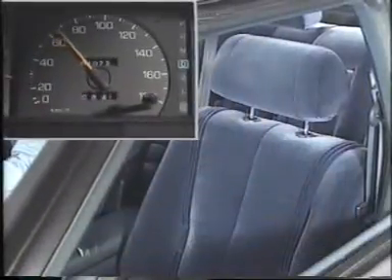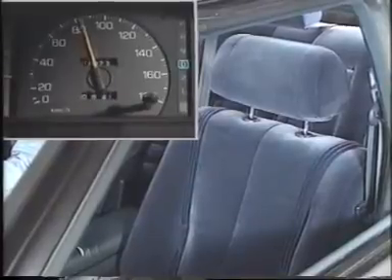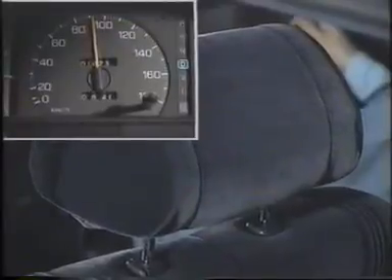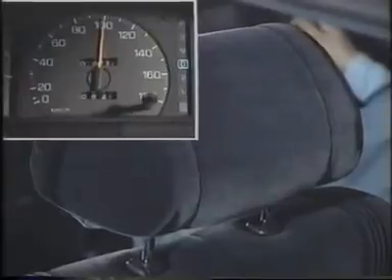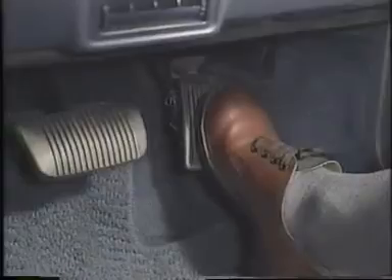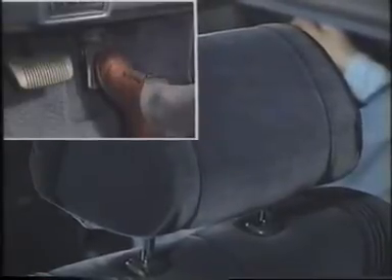In this case, you first begin to notice vibration when the vehicle speed rises to approximately 80 kilometers per hour, and the vibration increases as the speed increases to between 90 and 100 kilometers per hour. You also need to know the relationship between the body shake and the engine load. You accelerate, cruise, and decelerate the car repeatedly, but the vibration seems to be unrelated to the engine load.